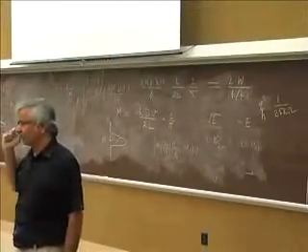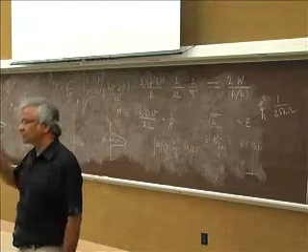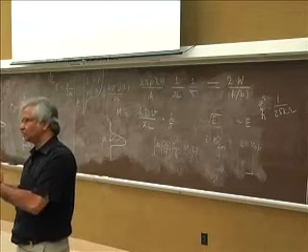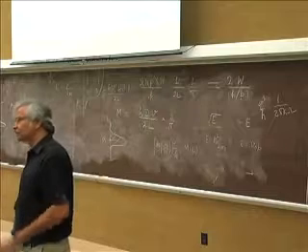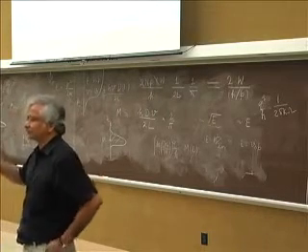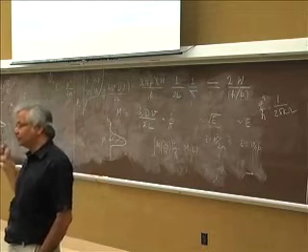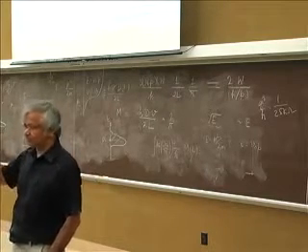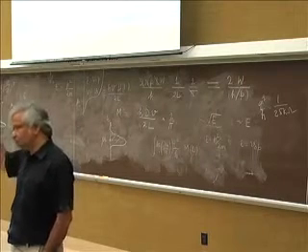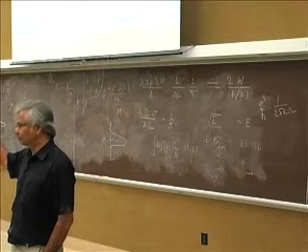The minimum resistance you get is actually 12 kilo ohms, more like 12.5. Why? Because there are always two spins in parallel. So that's the quantum of conductance, again, per spin, per mode. But then when you measure it in carbon nanotubes, you get 6 kilo ohms. Why is that? Because there are two spins and two valleys that go with it.